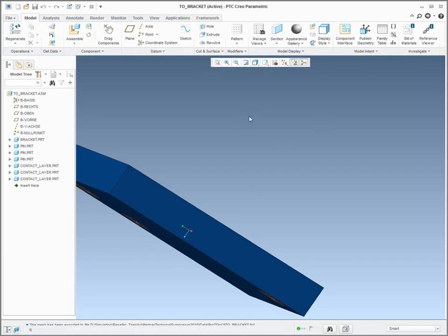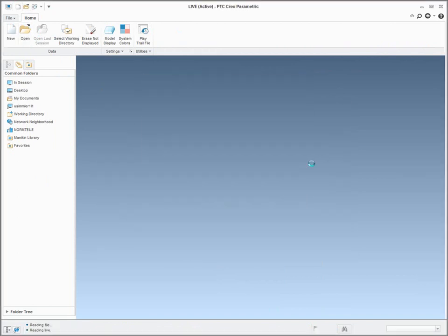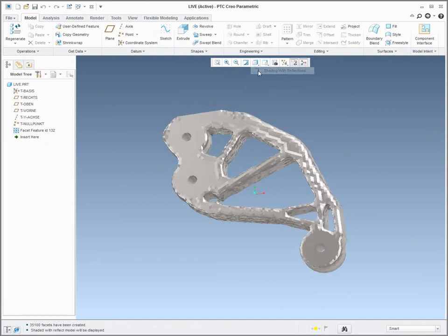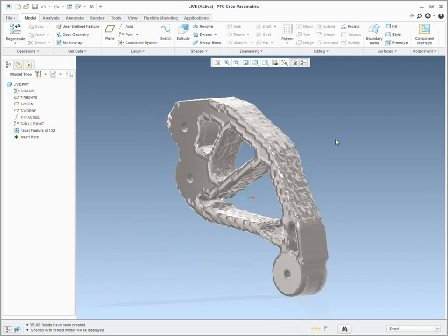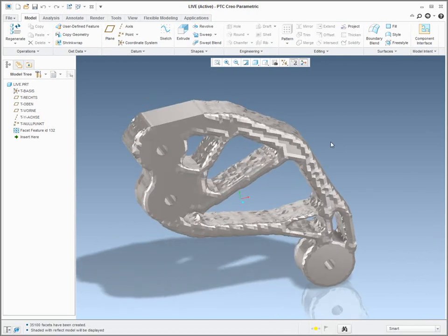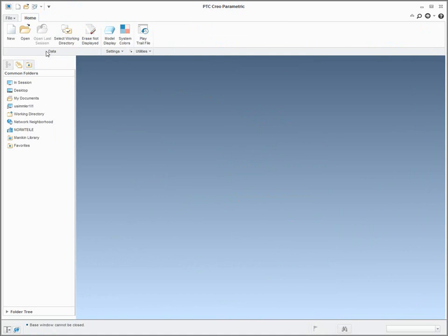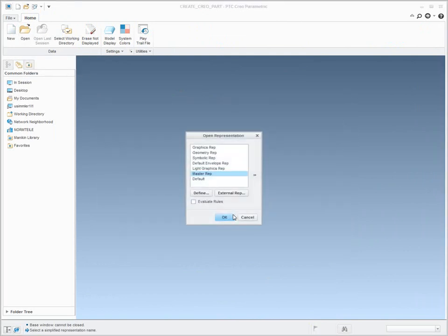And in Creo Parametric, I can open that component. I'm setting my filter to all components. I can see that STL file, and now this STL file will be shown here on my screen, and with the help of that STL file, I agree it's too coarse, I can reconstruct a new component, as we can see here in that environment.